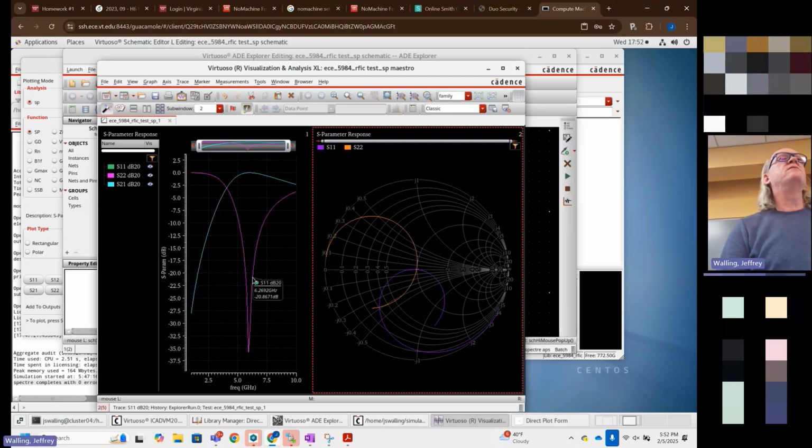Is there an intuitive reason for the relationship between Q and bandwidth? Well, what we're looking at is a tuned circuit, right? And Q is really a measurement of how well the circuit is storing energy relative to how much power it's dissipating. It's only going to do that perfectly, ideally losslessly, at one frequency if there's no loss in the circuit.